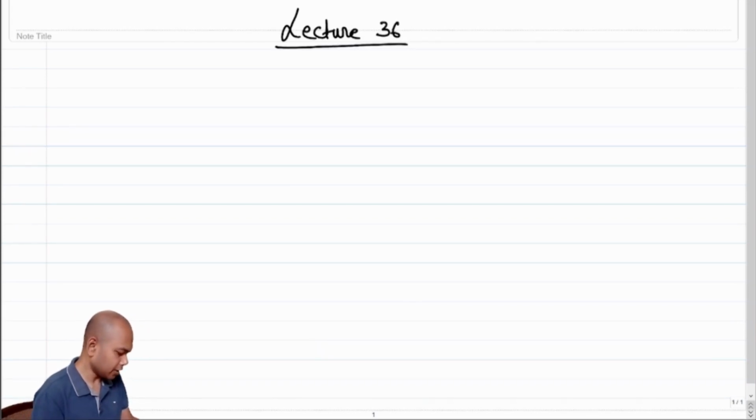So in the previous lecture we started seeing the frequency response of our common source amplifier, and the genesis of the frequency dependent characteristics of the common source amplifier was due to the inherent capacitances associated with the MOSFET. Before the last lecture, we kind of ignored the capacitances of a MOSFET, but in a design we cannot really ignore them, right? Since we cannot ignore them, we need to understand the contours till which the common source amplifier will work with regards to frequency, if the input is frequency varying.